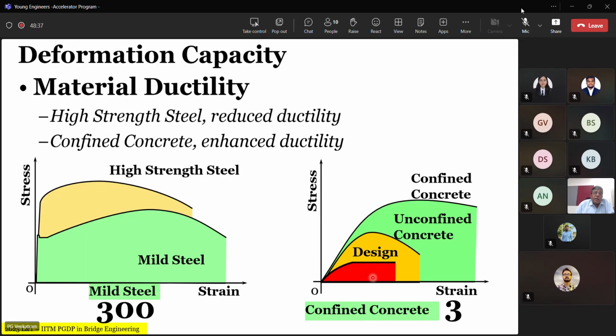Okay. So the ductility leads to what? Ductility leads to deformation capacity. All right. Now we come back to the deformation capacity, and I will repeat the old lesson: deformation is the reality and the stresses are the conjecture. That means we must have an ability to accommodate higher deformation.